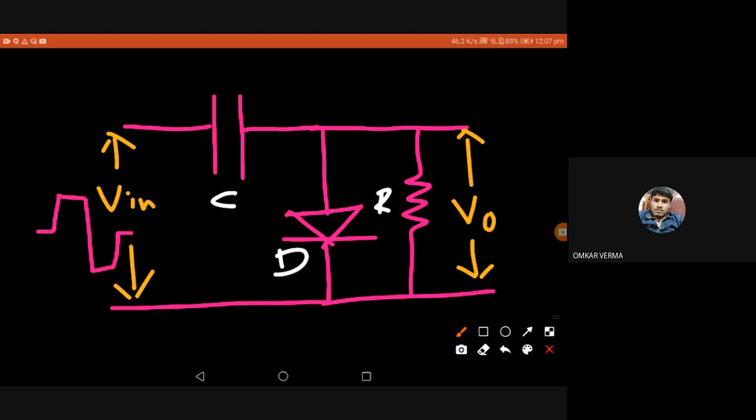Okay, we are clamping, I already discussed. We're clamping a DC over this input, and we get an output V0, which is the clamped input. So it is shifting the DC level without changing the shape or the appearance of the signal. And there's one question regarding charging and discharging of the capacitor.